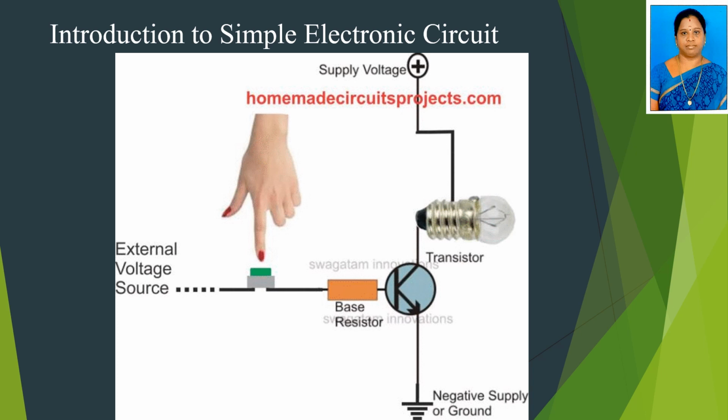If the bulb is connected to the positive as well as negative supply directly, the bulb will be permanently on, but we want to make it on and off. So if you want to make it on and off, we need a switch. As you all know, in home appliances we are using the tube light, fan, everything by pressing the switch, right? So in the AC case, we need two supplies, that is phase as well as neutral. One is connected directly to the appliances and another one is controlled by means of a switch. In a similar way here also, the bulb is controlled by the switch.